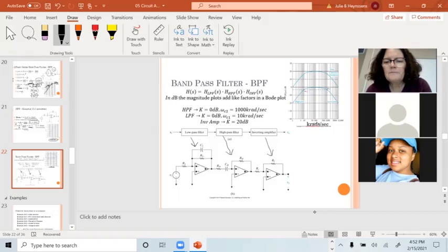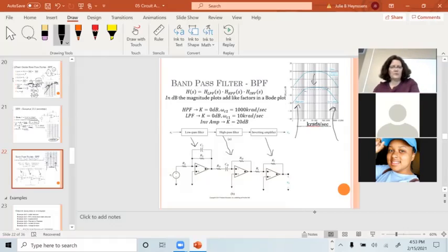So you have this high pass filter to filter out the 1 over F noise that's really high in your electronics, and to filter out whatever noise the ghosts are making. I'm sorry, I can't resist that anymore. You have a low pass filter to filter out the high frequency components, and you have gain in the middle. And you can put those together, and that's kind of a silly way of building a bandpass filter. But it can be done by just cascading stages.